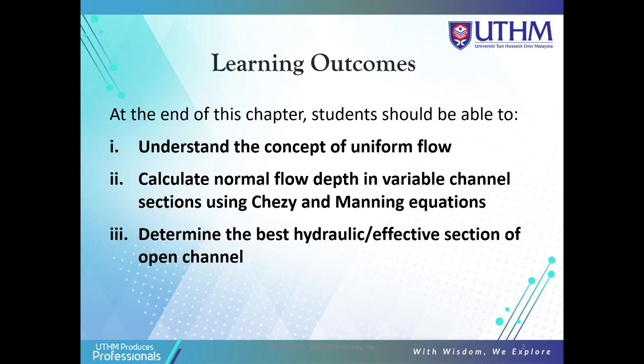Today, I will teach chapter 2, uniform flow in open channel. At the end of this chapter, students should be able to understand the concept of uniform flow, calculate normal flow depth in various channel sections using the Chezy and Manning equations, and lastly, determine the best hydraulic or effective section of an open channel. We have covered the basic equations in topic 1.